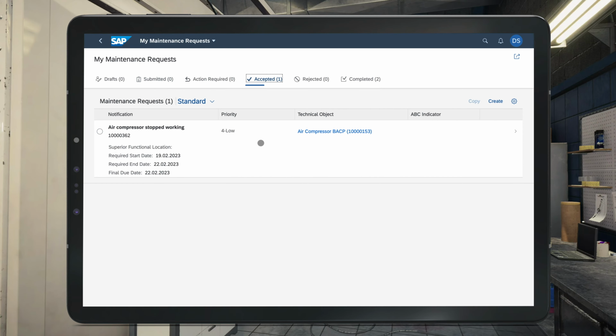For this purpose, I launched the Manage Maintenance Planning Buckets app. Here we have to define the bucket first, so we will use the button create. For this compressor, let's call it maybe maintenance of paint area assets. Actually, it can be a description and a label. It can be maybe TX01. This is the plant number, TX01 paint. Let's do it like this.